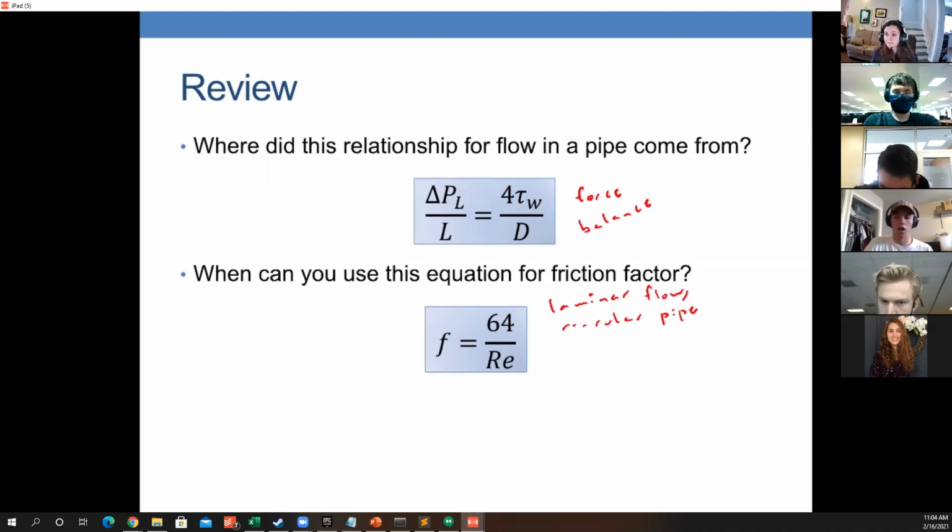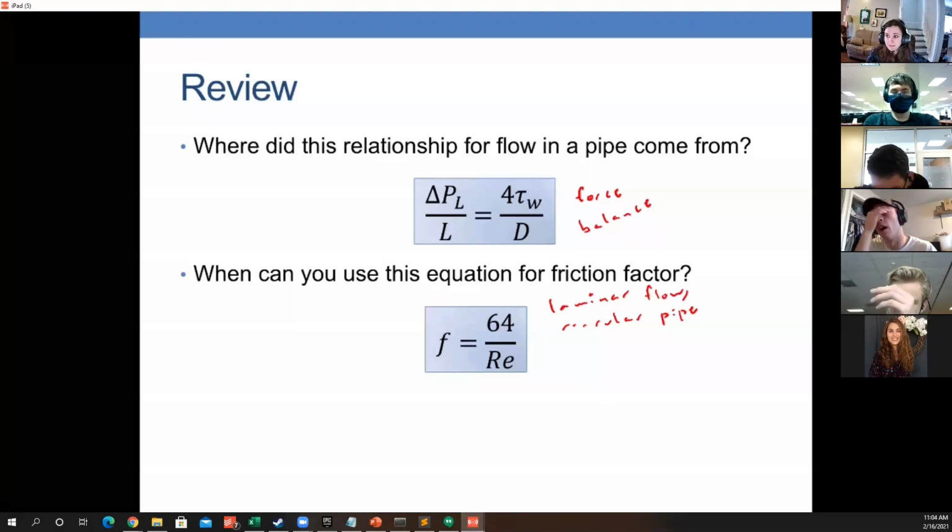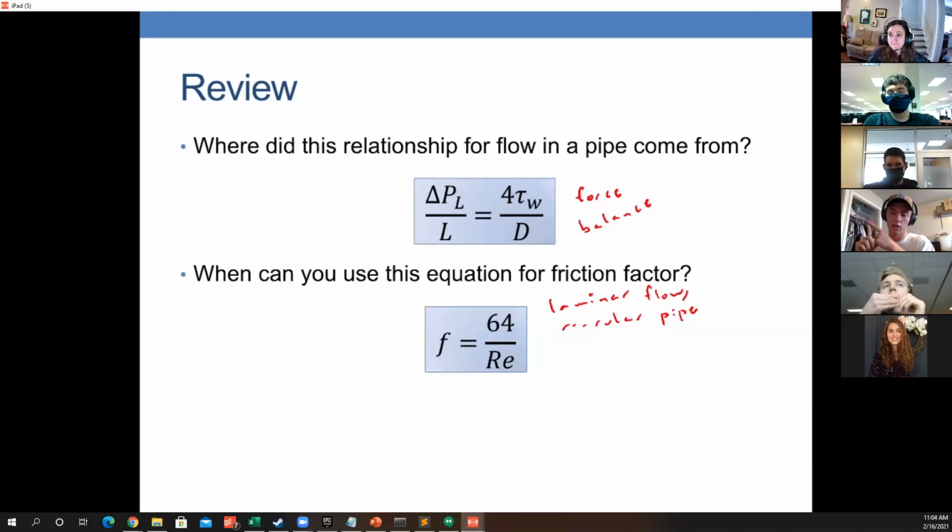Dr. Nickerson? Yes. I'm kind of confused about, say you have a pipe and there's no velocity change and no height change. I'm confused about how you have a change in pressure term and also a pressure loss term. So I guess the relationship is, if there's no pump, then the change in pressure is equal to the loss. But if there is a pump, the change in pressure will be 0, and the pump and the loss will be equal. Am I saying that right?